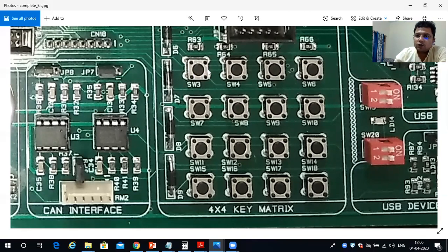First, corresponding to this output pin, we will make the value 1. Then in the same for loop, once again we will make this as 1. At a time, only 1 column we will make as 1. So suppose corresponding to column number 3 in the loop, the value is 1, and at that same time you have pressed this switch, then at the same time the row value will be 1. So if your row is 1, then we will check the corresponding column number, because that is in our hand, that is inside our loop.